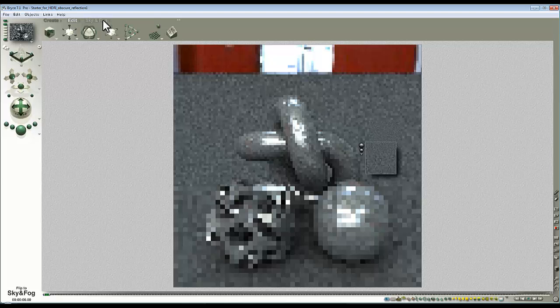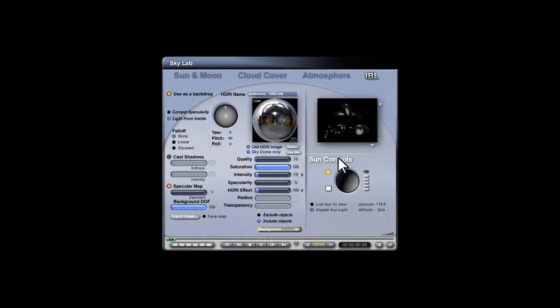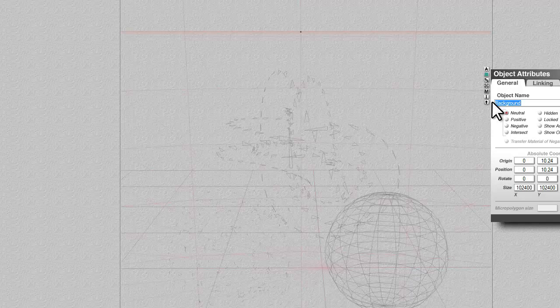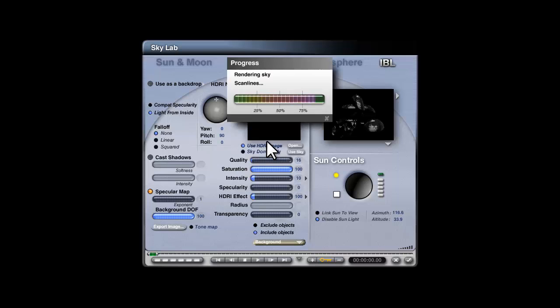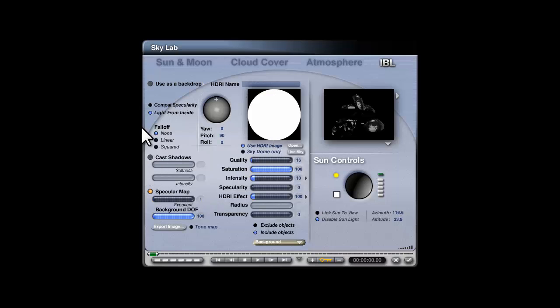Oh, potentially then we could light it with just white. So, but I've set the atmosphere to fully white, and you see what we're doing here is this is background, so this is just a target for the light probe I'm going to create. So if I use the sky and create just fully white, I won't make it a sky dome, I'll make it a full sphere, and it's lighting from the inside, and it's targeted onto background, then I'll just have to check that we've got true ambience optimization disabled, because it turns itself on by default.